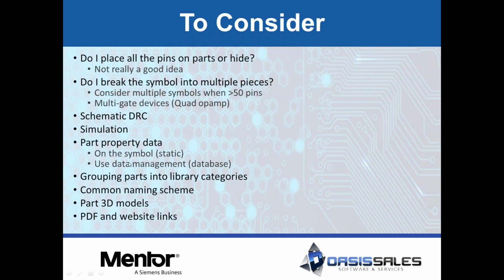Part property data. Don't put part property data necessarily on your symbols. It becomes static and old. Use data management tools that you have access to. All of our Mentor tools that we sell anyway come with data management applications except for PADS Logic. So take advantage of the tool. It's there for you. Use it. I'm going to show you some database tools here real quick that you can download for free, and they're very simple to use as well.